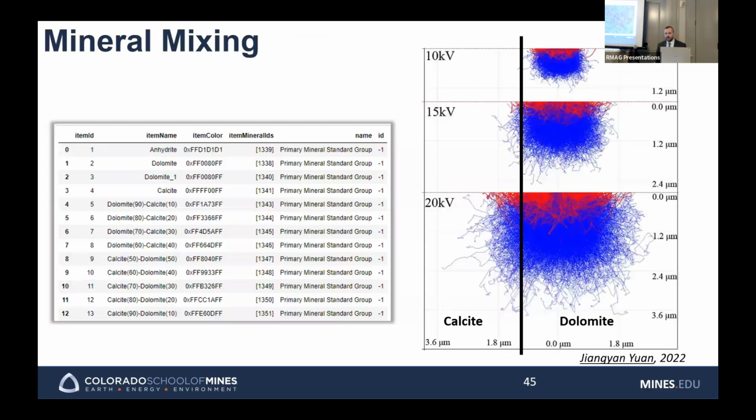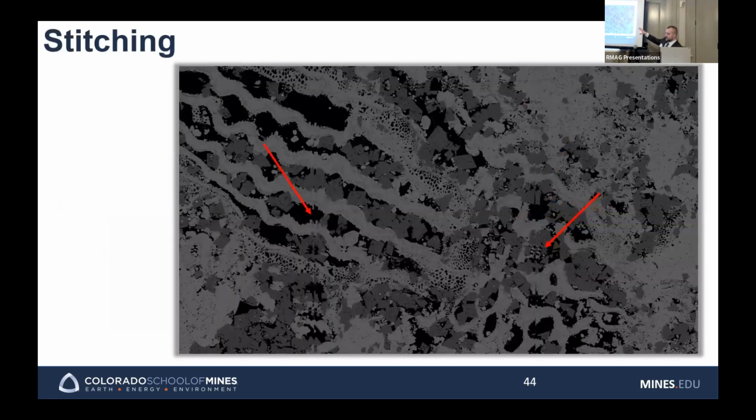Yeah. So you can see that when the SEM does this, it does it in fields of view. Everything is just a small rectangle, and then you ask the software to try and stitch them back together. I tried to use red arrows to show these vertical and horizontal streaks that run through the image, where it looks like it's off, it's blurred. What happens is if you export this without stitching the image, all of a sudden it's tripling or doubling your pore numbers. Or if a pore is supposed to be a perfect circle and it's not stitched correctly, it'll be offset, so now the shape and count of that pore is incorrect. So I felt like it would not have been valid data without the ability to stitch.